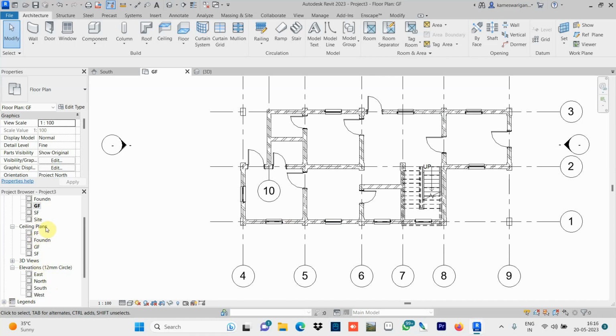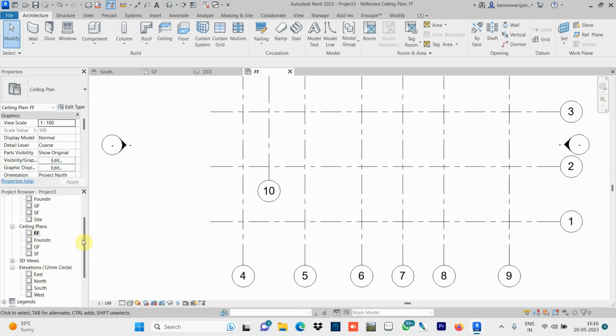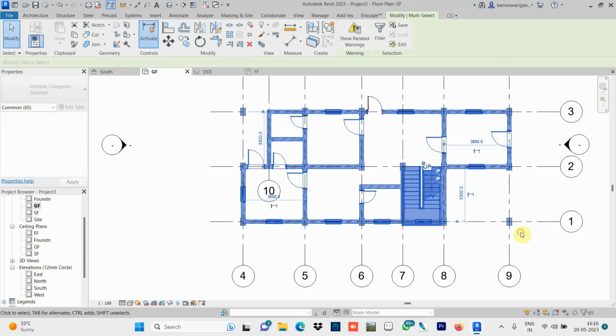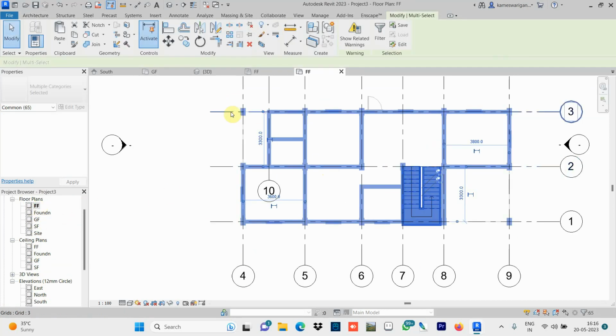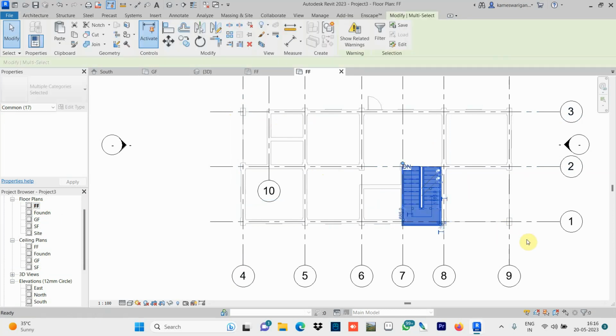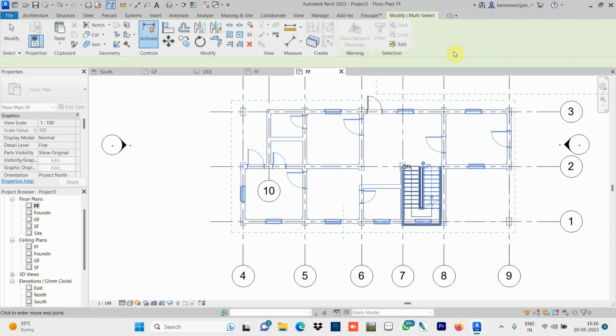So now what you need to do, while you are going for this slab elevation and ceiling, ground floor, ceiling fan at the ground floor, at the first floor. Okay, so the plan will be the same. So remember what is there in the ground floor, the entire thing you copy, Control C, and you go to the first floor, and the entire thing you put it here, Control V. Okay, then you save it.